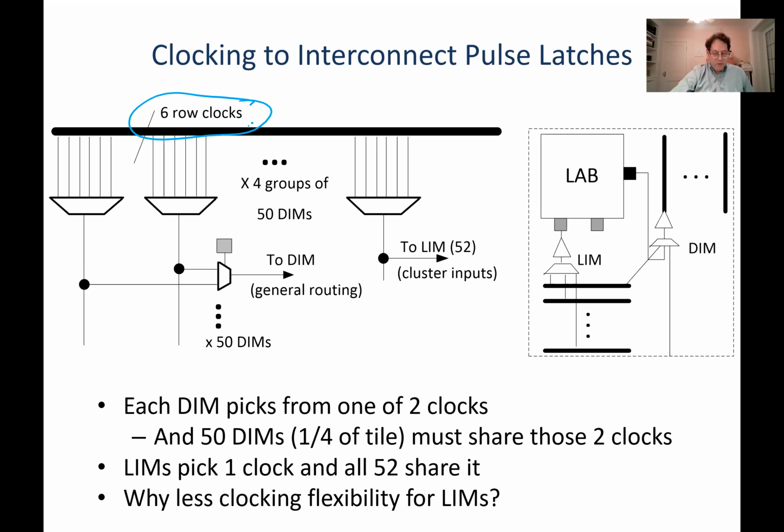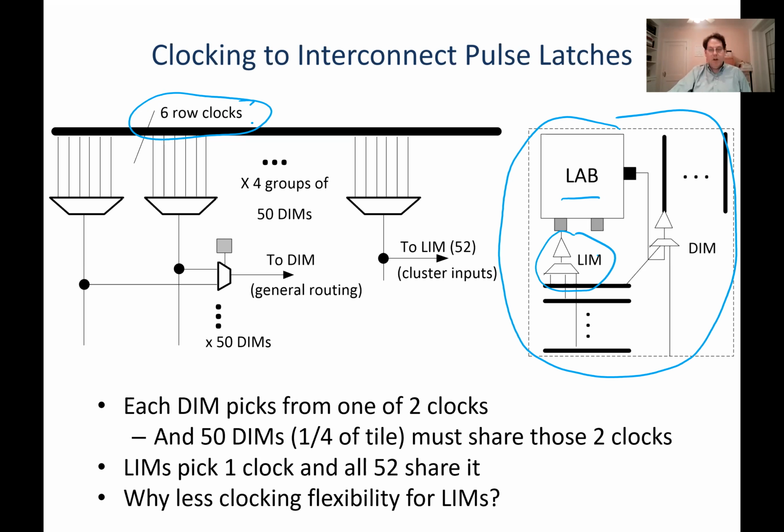But now with these registers, the clock or pulse latches they've added to the interconnect, they actually have a whole bunch of routing drivers in the same area as a logic block. So this is their basic tile. The basic tile is a logic block, which they call a LAB. They have a whole bunch of what they call LAB input muxes; those are the input connection block muxes. And they have a whole bunch of what they call driver input muxes. Driver input muxes are the direct drive switches, so a mux and then a driver that can't be tri-stated.